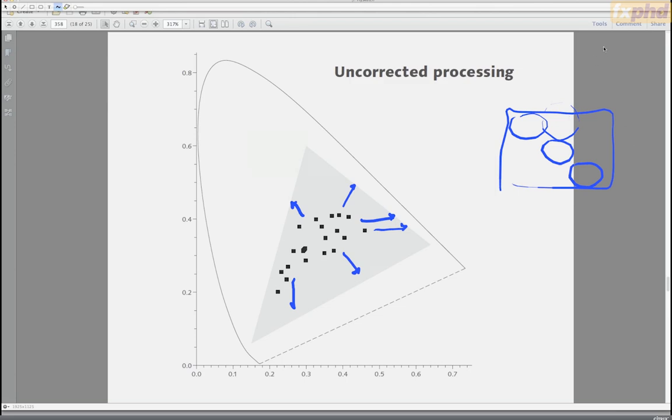For example, I explained to you that the red channel will probably want to be produced with a fair bit of negative green. So we're going to come into this matrix with RGB, and the red coefficient is going to be some fairly large number. In fact, it might be as big as maybe 1.4. But we want some minus green, maybe minus 0.4. And this will be built into the matrix.